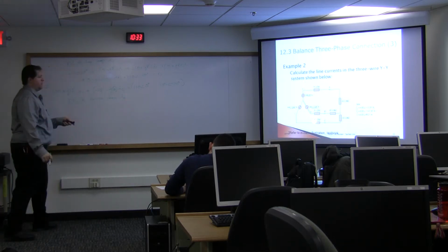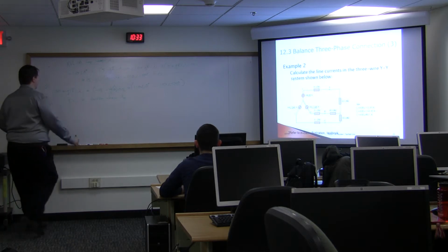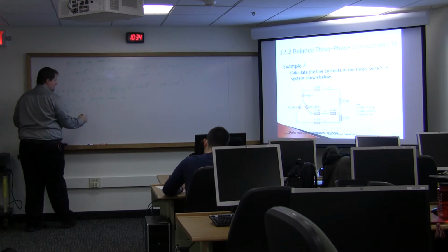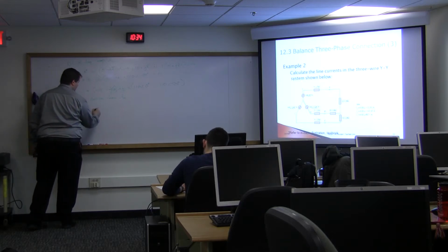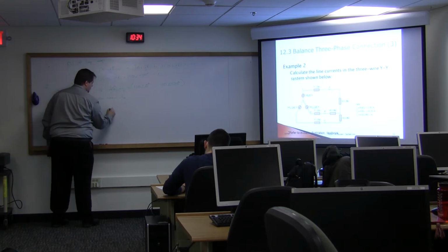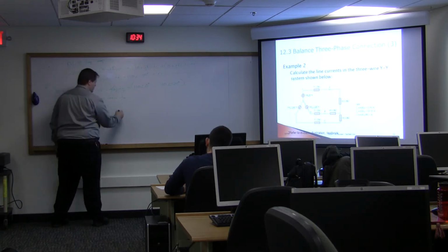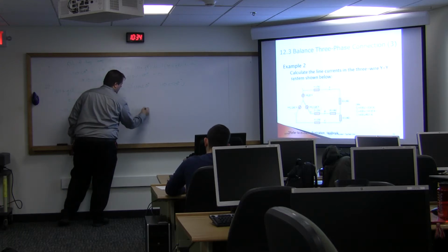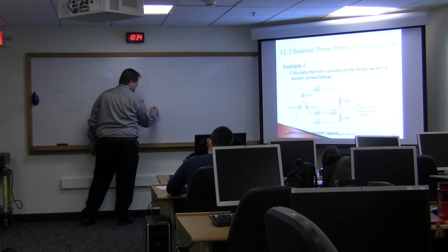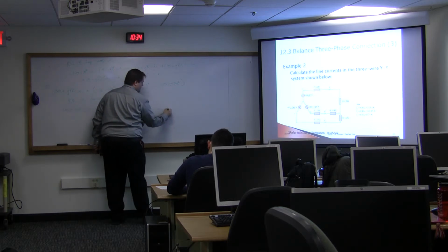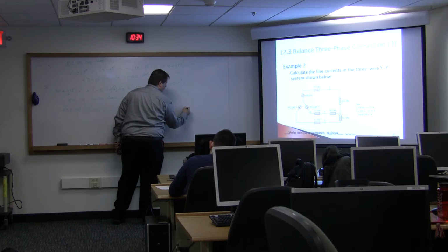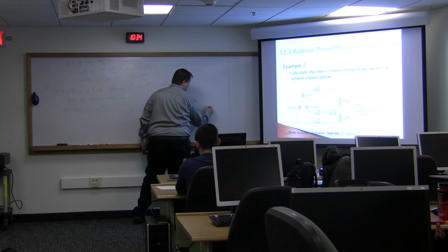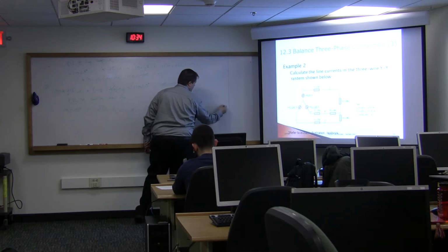If I do that, you can see if I were to start here, I'd have a very, very similar equation: 110 with a negative 120 degree phase, plus 5 minus J2 times I2 minus I1, plus 10 plus J8 times now I2 minus I1, plus 10 plus J8 times I2, plus 5 minus J2 times I2, plus 110, phase of negative 240 equals 0.